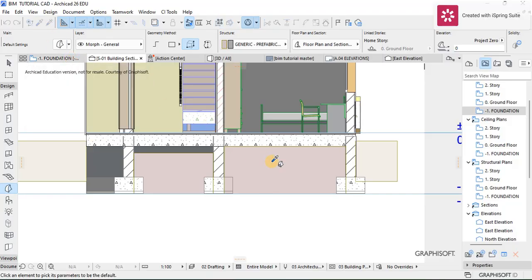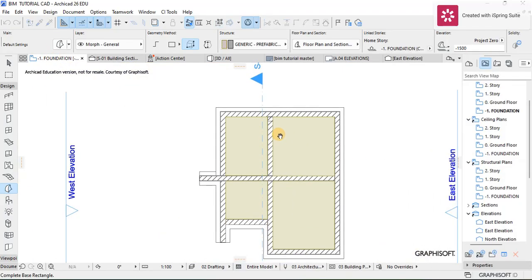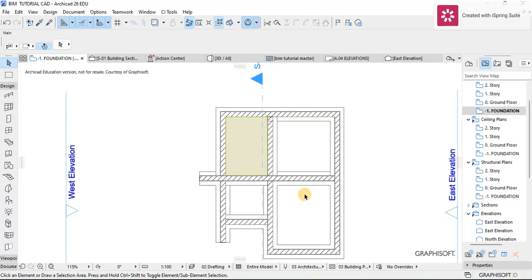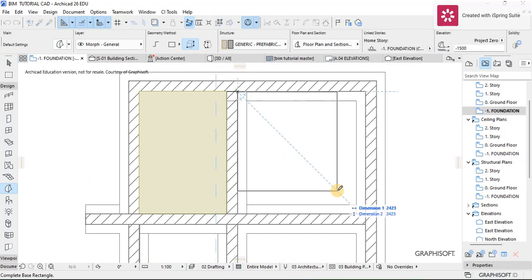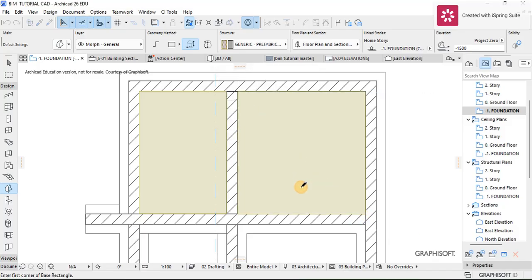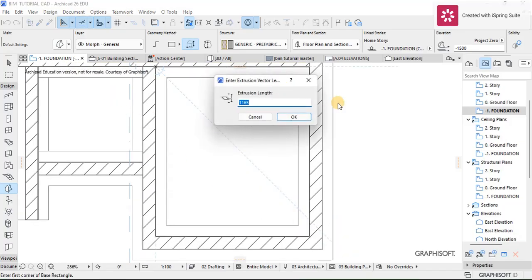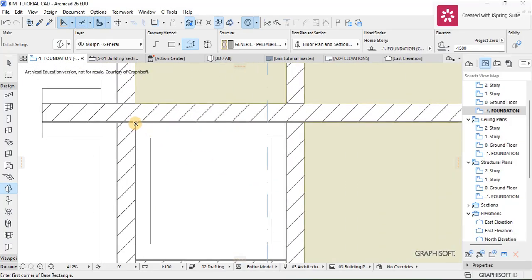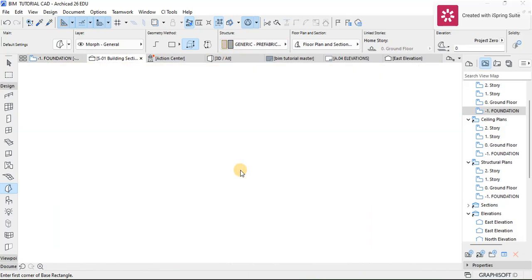So I'm going to do the same with the rest. I'm just going to have to pick some attributes from these, and maybe select it there. Actually, don't change it. I just have to do it again. So I'm going to shift everything, and then I'm going to backspace them and put the right height for my backfill. Remember, this is a strip foundation, so there are limited backfills you can use. Say OK, and draw this out again. Then I press OK. So we have our four backfills, and in the sections you can see they're actually full.